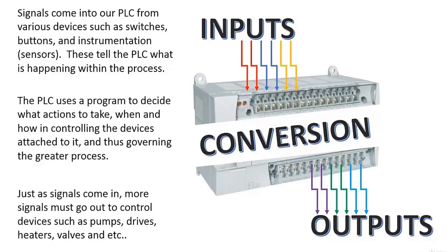called inputs. And one of the first things that a programmer needs to understand when they're first learning about PLCs is I/O. How do I get information into my PLC, and how do I control things around me? Without I/O, if we had an isolated PLC, it really wouldn't serve any purpose that a computer couldn't serve, and probably much better. So, by necessity, if we're using a PLC, there's got to be some signals coming in and/or